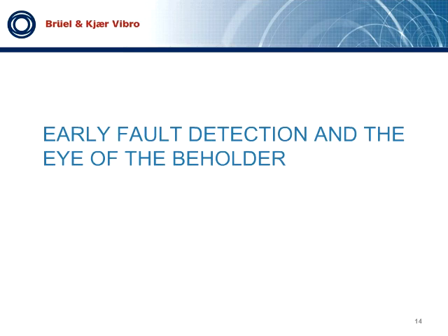So, what is early fault detection? Now, there are fault signatures seen in the vibration data which cannot be seen with the naked eye. This could be subsurface cracks, for instance. This will cause load variations, which are picked up by the vibration sensors. And very often, this could trigger the CMS analyst to even issue a report.